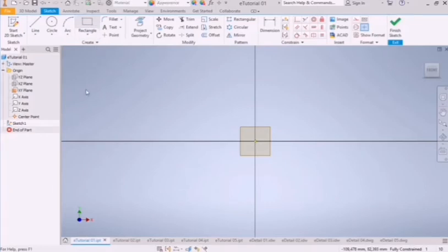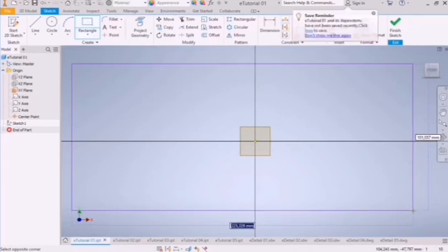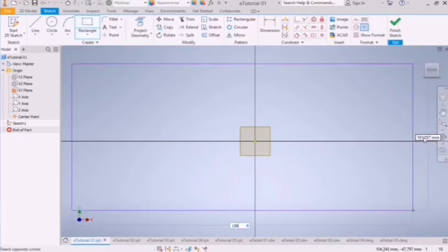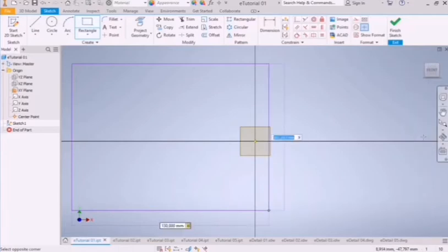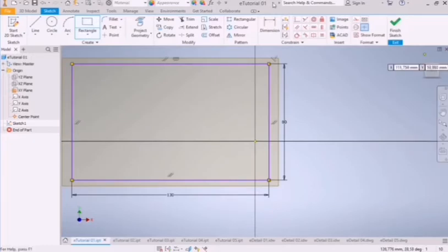Click the rectangle, activate the rectangle, and then just draw anywhere, as you can see, it's highlighting the horizontal where we can edit. Then from the question paper, let's say this is 180, and click there the height. Let's say the height as per question paper specified as 80, and then click the enter button. So that's another way of doing it.